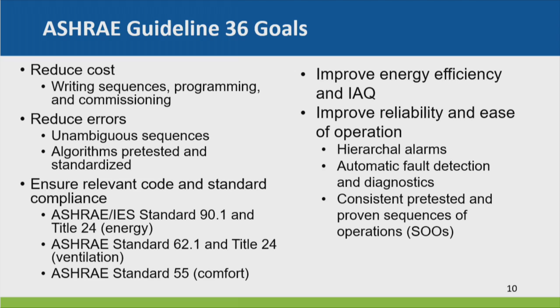in the guideline that I'm not going to really talk about that much is the alarms and fault detection. It's amazing, our controllers are fancy little computers, and we use a tiny, tiny percent of them, right? Probably like most of us on our phones, you use like 10% of its capability. Our DDC systems are the same way. We don't use enough of it. We can build diagnostics and fault detection into our controllers right now. And by doing that, you can get a lot of the benefits of fault detection, where it says, hey, this valve is stuck open, and you can go and fix that. So we have that in there as well.